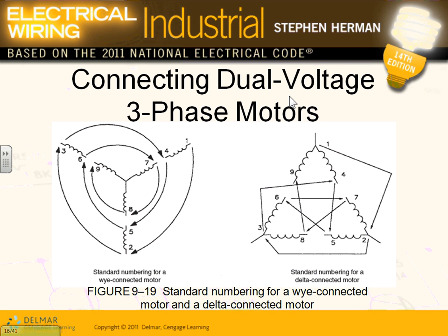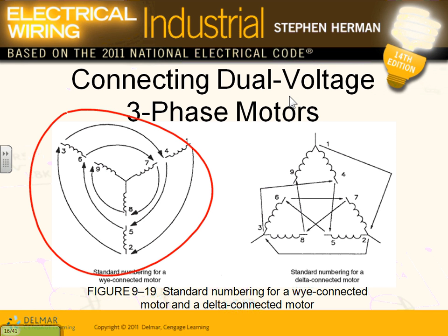Good point, though. Okay, the other thing, guys, I'm not going to go through how to identify. This is when you wire. You guys went through this with Gary. This is how you identify a three-phase motor. Here's what I want you to understand. Almost all three-phase motors come this way, a Y, with 9 leads. They call them 9 leads. All of them come with 9 leads in a Y. Some motors come delta, but most motors come this way.